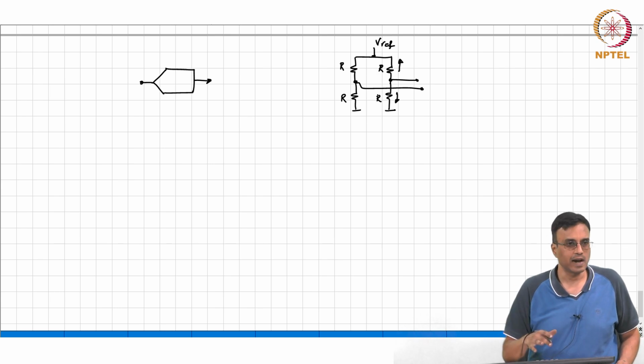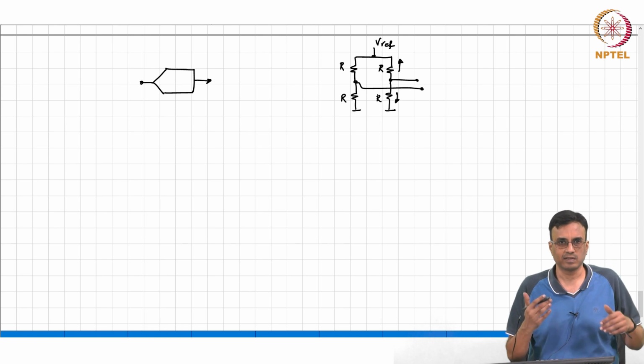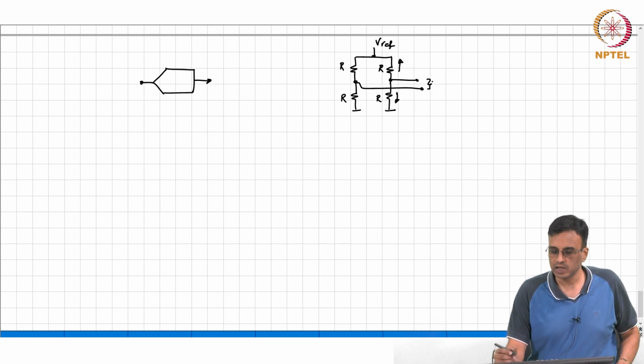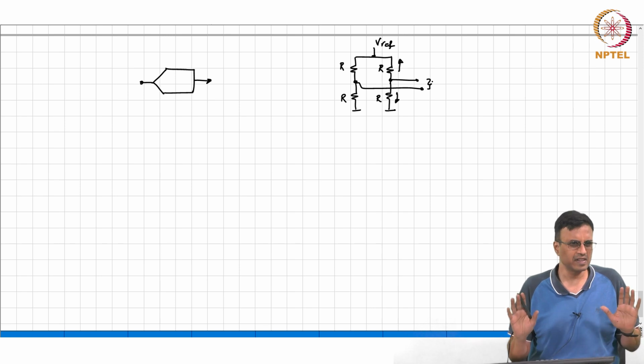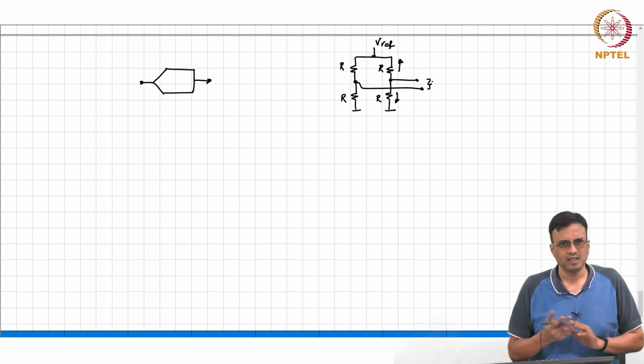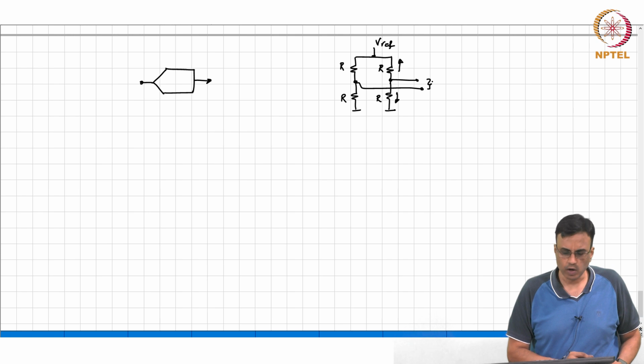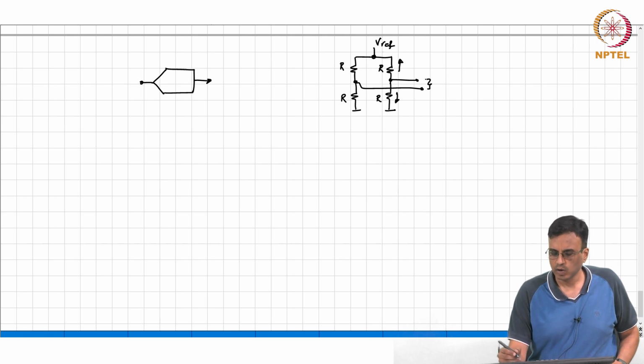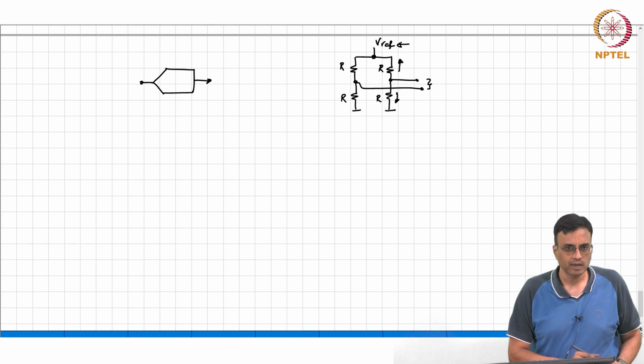If you stand on the weigh scale, one resistor goes up, one resistor goes down. So, the difference in voltage between those two leads basically represents the weight that you are putting on, and clearly that difference is dependent on the reference.